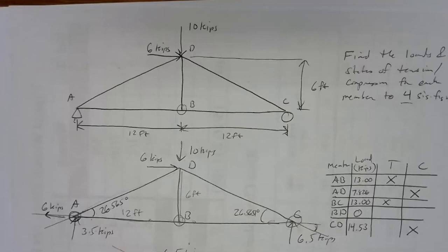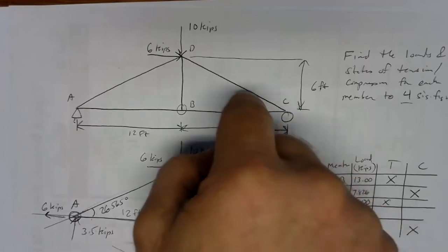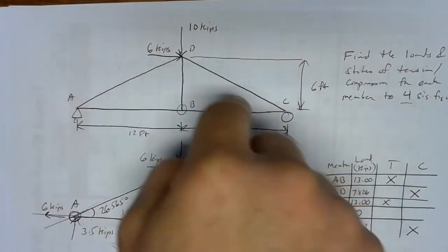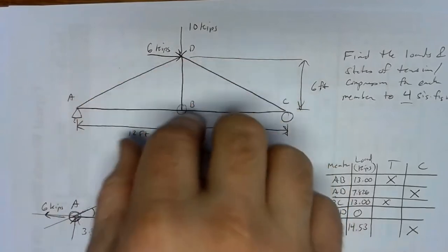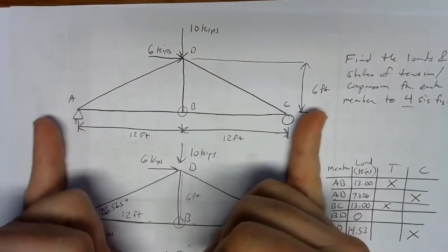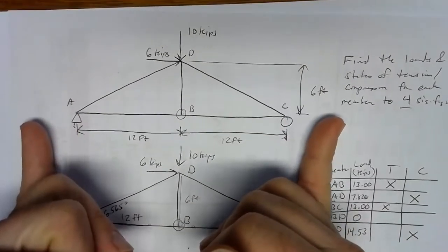If we didn't have those there, and this happens, if you're familiar with residential construction, you might be familiar with things like cathedral ceilings, where people try to build a ceiling that kind of goes up to the top. Well, if you don't get that exactly right and you don't have enough structure there, things like snow loads and forces pushing down can actually push the walls of the building apart.